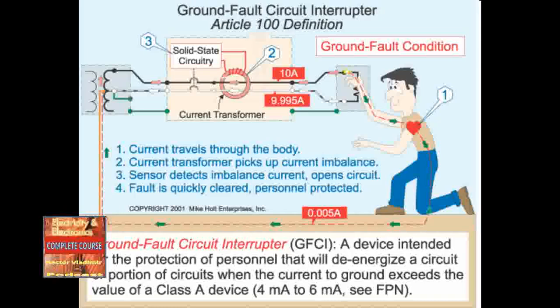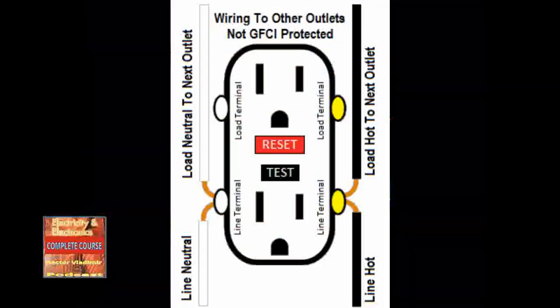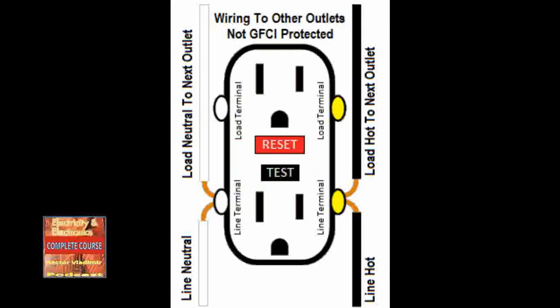After the GFI is tripped, the red reset button needs to be pressed to reset the GFI trip mechanism once more. See Figure 2-22. Be aware of a condition known as the nuisance trip, which occurs when there is excessive moisture in the device area.